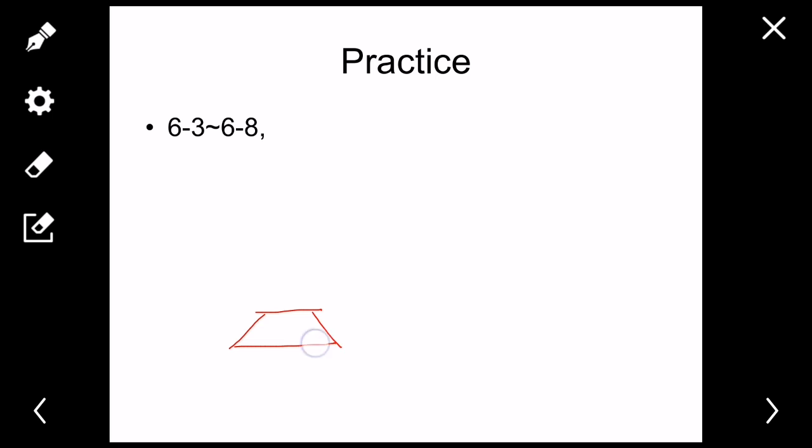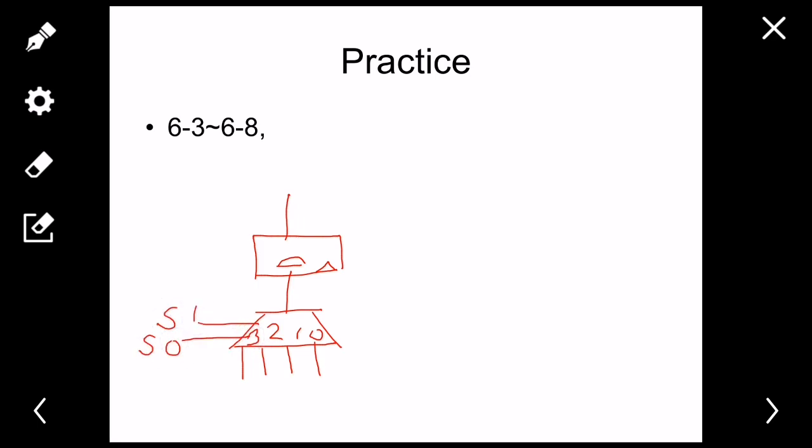We know that a 4 to 1 mux has 4 different inputs and one output, and the output goes directly towards the input of a D flip-flop. Okay, and there will be the output. And there are your select pins S1, S0, through which we can select our modes, or the functionality of the circuit. So this is the thing we're going to do.